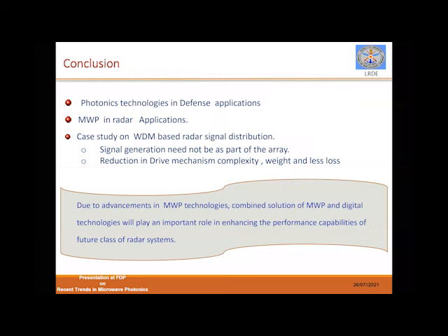What type of optical fiber is used in radar applications? Most of the time we are using single mode fibers which can operate in the 1550 range. Did I answer your query? Is it single clad or double clad? Commonly any rugged type of cable with a single clad itself is more than enough. For WDM application, it is also single mode.